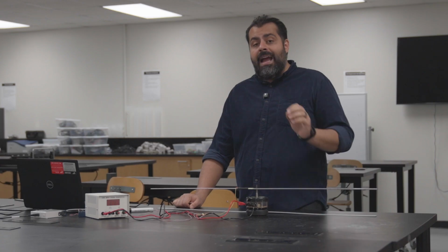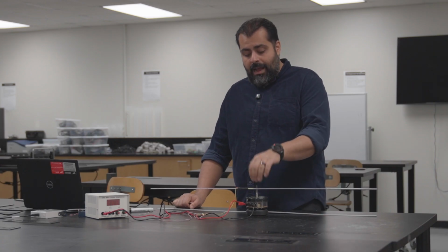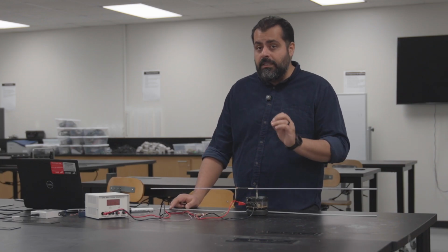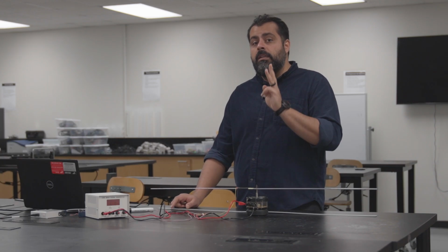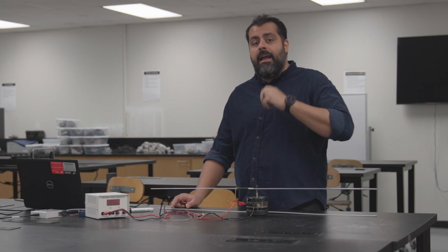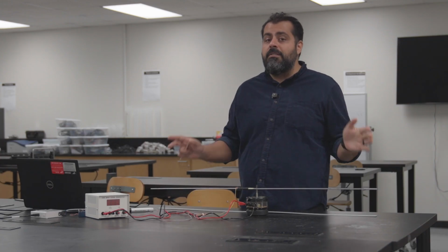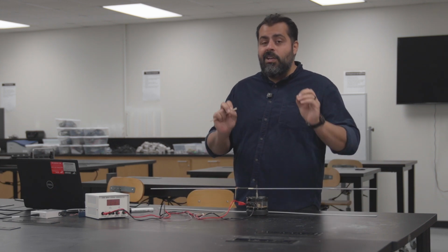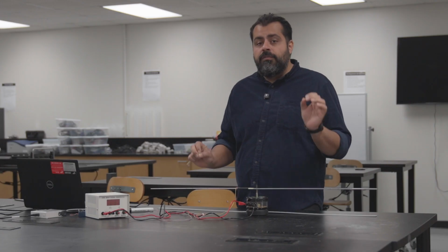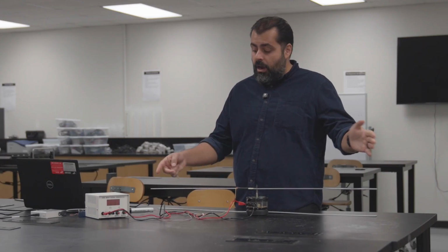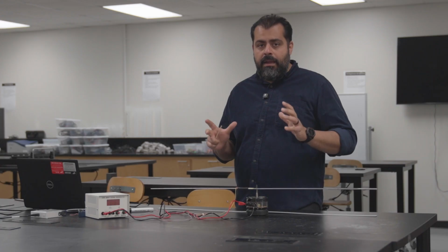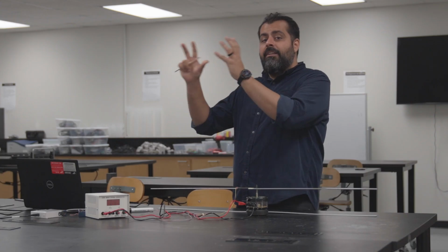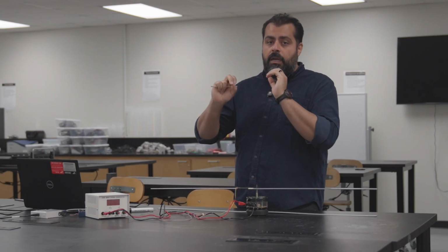Then we are going to ask you to run this shaker and this beam at the three natural frequencies for the cantilever beam, and the three natural frequencies for the free beam. For those natural frequencies, we are going to ask you to find the node locations on this beam and compare them to the theoretical values for the cantilever beam and the free beam, right?